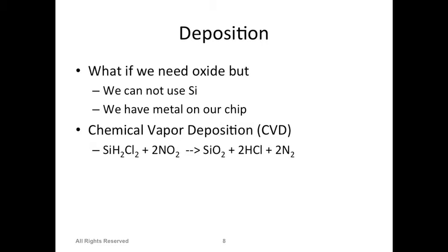And again, if you do the CVD process in an air environment, a regular air furnace, it will not be good, because in air you have a lot of debris and other gases, and they will also start reacting with your layer. So the layer which will be deposited will not be good enough. So one thing, we have to have a chamber which operates at a very high vacuum, okay, low pressure. So very high vacuum, that's one condition.